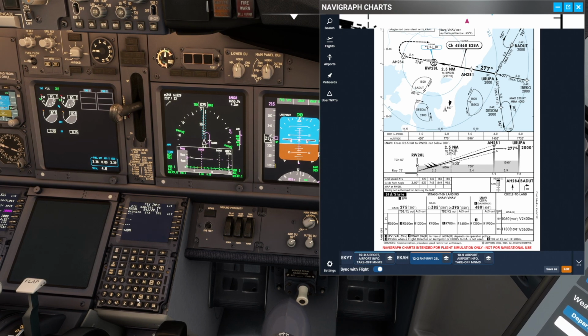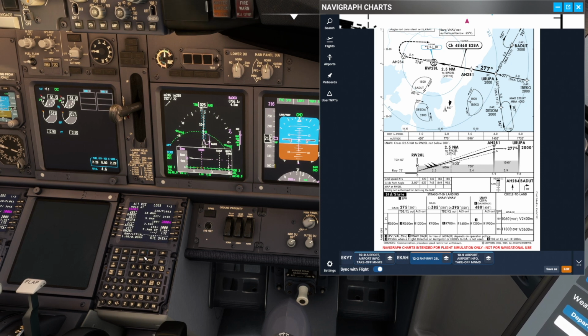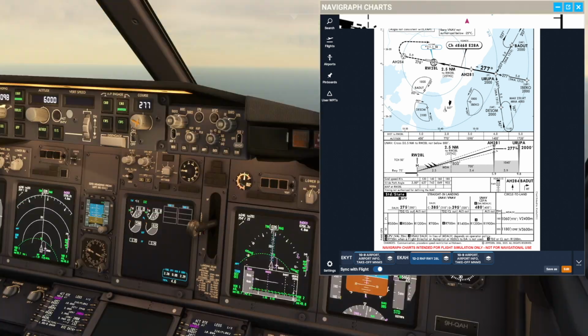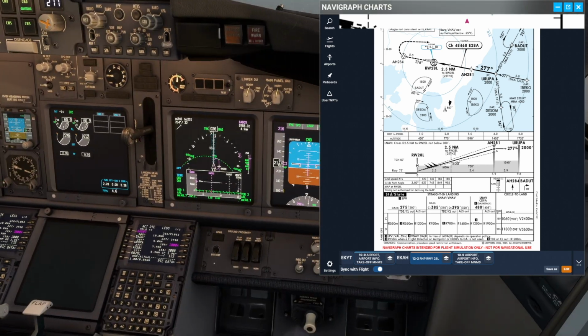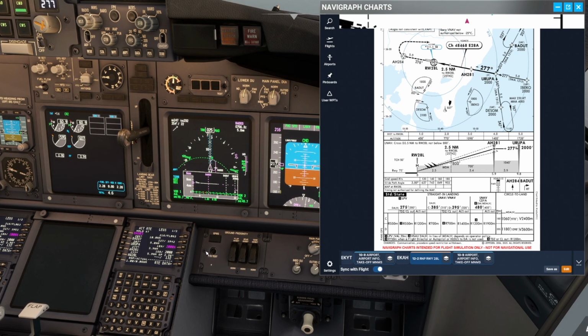Runway point we have, 4-mile point, 10-mile point. We don't need a descent point today. I'll put a 25-1 just for reference, just to know how far out we are. Good. So we have the frequencies, we have the rings, we have the idents, we have the standby altimeters and courses. 277, 277. Good. So let's talk a little bit about VNAV.